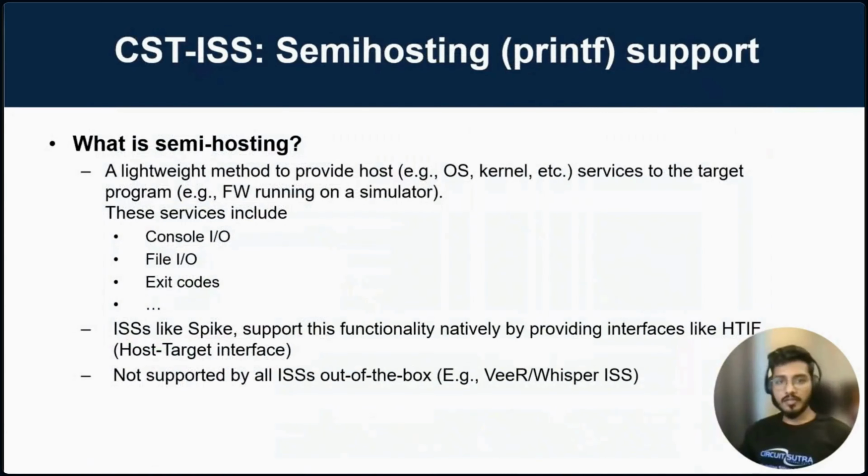So what is semi-hosting? Semi-hosting is a lightweight method to provide host-target interactions. Host can be an OS kernel, and target is the firmware running on the simulator, which includes console input-output, file input-output, exit codes, and system calls, for example. ISS like Spike support this functionality natively by using HTIF, but this is not supported by all the ISS out of the box.